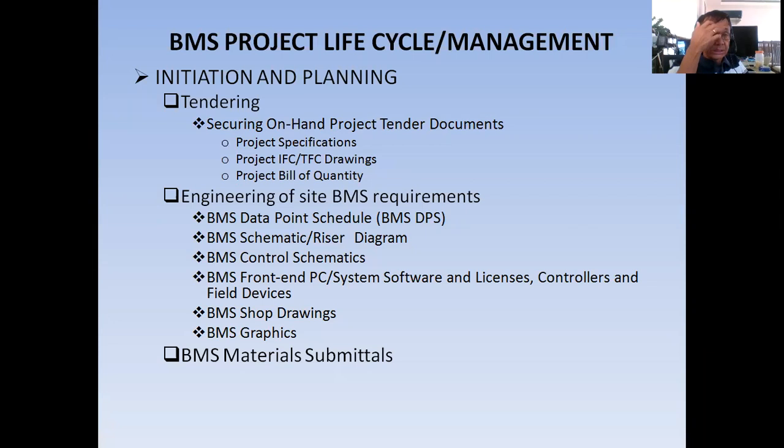As I explained in my previous video tutorials, you need to religiously go one by one and check all the requirements of BMS in all these project specifications, especially in mechanical, because the bulk of BMS points you can find in the mechanical specification for controlling the HVAC equipment.